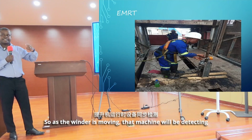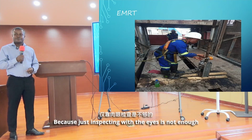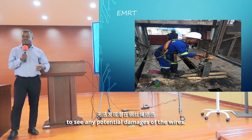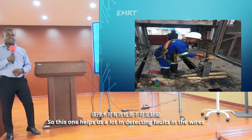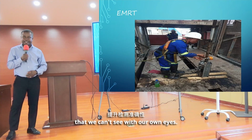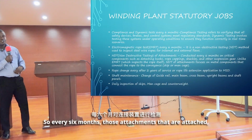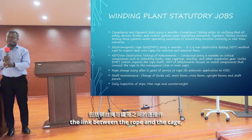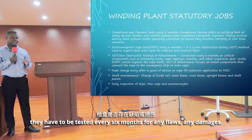that machine will be detecting internal and external defects in the wire, because just inspecting with the eyes is not enough to see any potential damage to the wires. So this one helps us a lot in detecting faults in the wires that we can't see with our own eyes. Then we've got non-destructive testing of attachments. Every 6 months, the attachments, the link between the rope and the cage, have to be tested for any flaws, any damages.